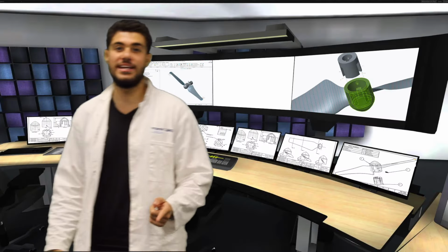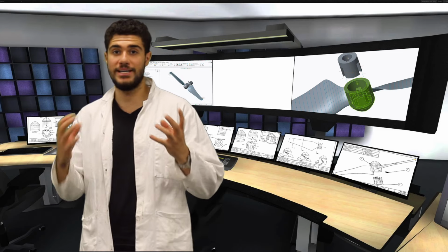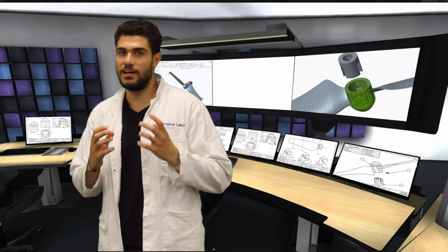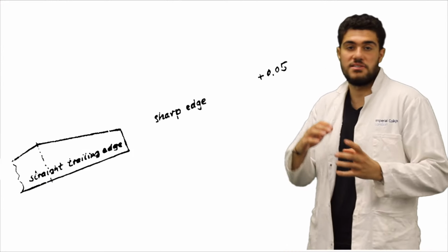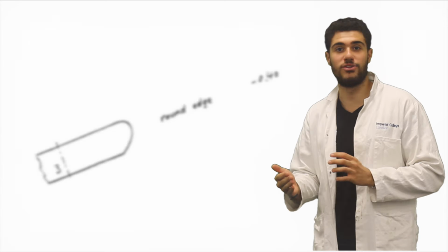A great deal of thought was dedicated to the design of the blade tip, as a poor design would significantly decrease the overall blade efficiency, and with such massive potential efficiency gains, a good tip design is a must. Various iterations of the tip, such as simple side tapering or a curved finish, were considered, as well as their effect on the power coefficient. We were looking for a design that primarily mitigated the effect of tip vortices, but also increases the power and the efficiency.